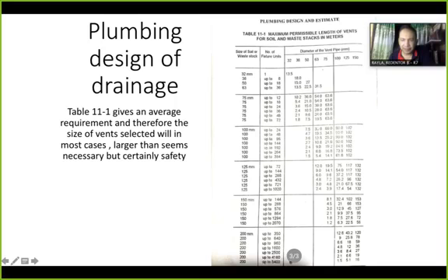So you need to account for the number of fixture unit. Now, for example, toilet, 6 fixture unit, 4 fixture unit, plus laboratory, 2 fixture unit. So you need to add all. So if the total is 5,400, you will intersect here along this line.